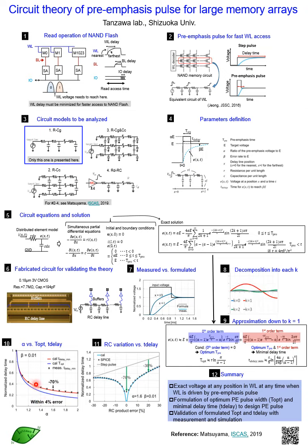And if you apply that pre-emphasis pulse, then you will have the minimum delay time, as shown in the red curve. This mark shows the measured result, which is well matched with the theory within 4% error at maximum.